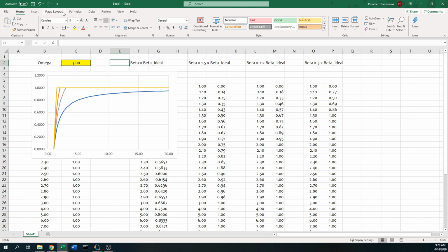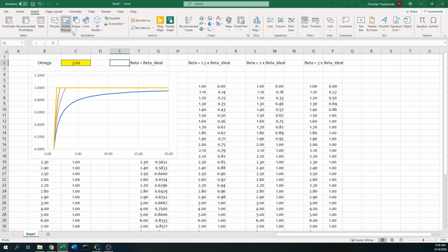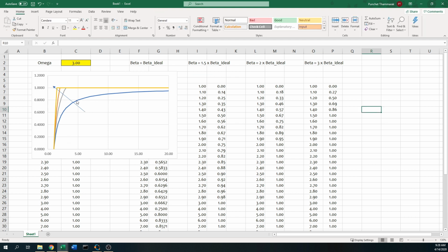Behavior just looks improved, right? It improved. Wait a minute, I need to draw into this direction. So the less brace stiffness you provide, the softer the system, and it takes forever, infinitely large lateral deformation, in order to reach the 1.0 P over PE ratio. That is bad, and you do not need this in your design, because you are going to need quite a large bracing force. The capacity of the brace will be really large. It's not a good idea to do that, and your structure will badly deform. That means it is not usable.